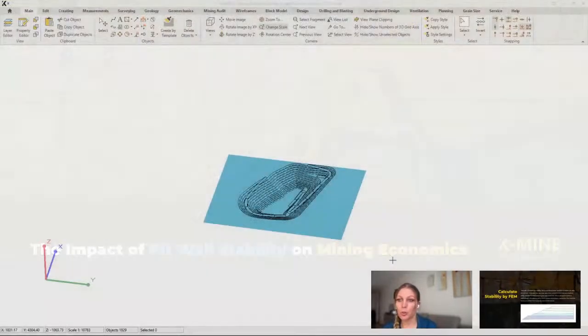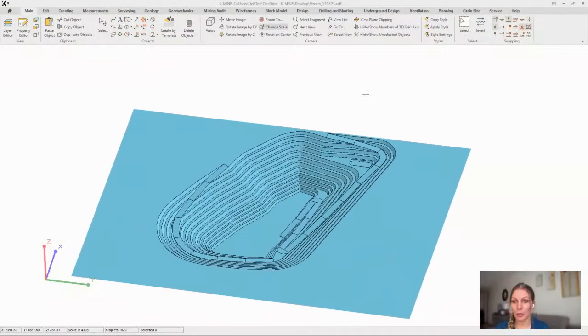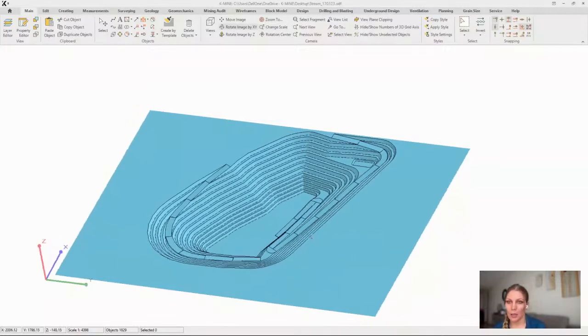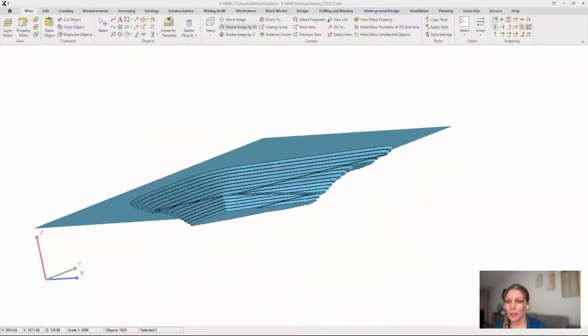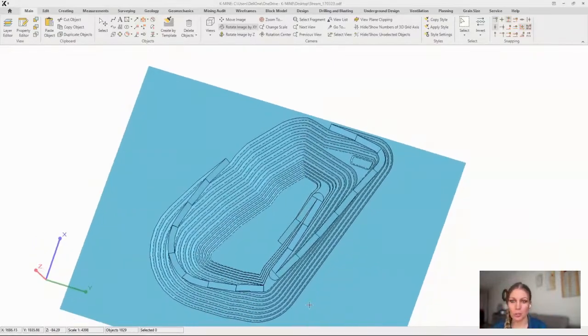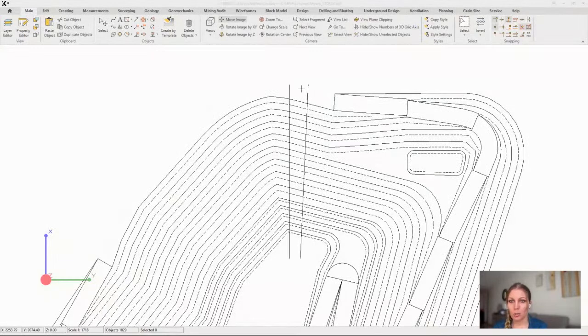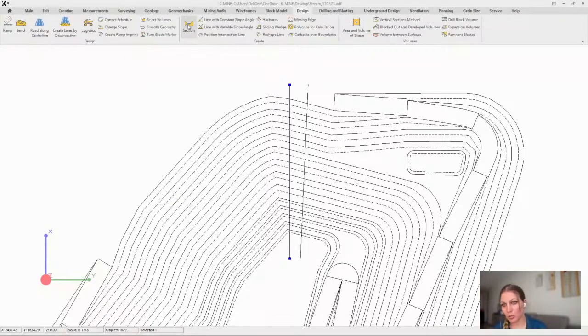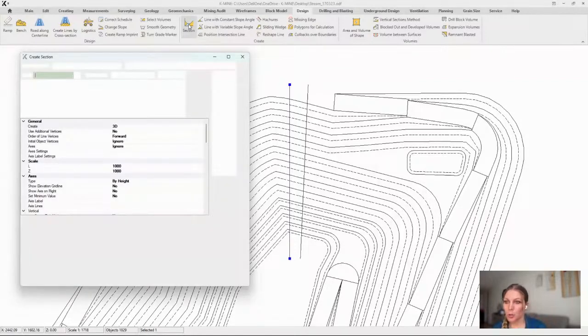So now we can explore the geomechanics model in K-Mine in a more practical context. Our objective is to optimize the angle of inclination of the pit wall to achieve an economic benefit. So to start, we'll determine the current stability coefficient and then proceed to optimize it. First of all, we make use of the initial design coordinates of a conditional open pit, as well as the framework of the open pit and the rock formations that contain the mineral deposit.